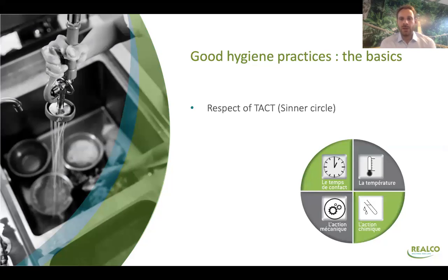Again, the basics. When you have chosen a chemical for the cleaning or a sanitizer for the disinfection, you are going to apply them. And in fact, you need to respect what we call the Sinner circle. For the presentation, we call it the TACT, because it's just an easy way to remember the 4 parameters that you need to respect absolutely to be sure that you are going to have a good cleaning and sanitation. So the TAC means time, action, concentration, and temperature. They are the real 4 important parameters to follow. And I will explain that with the next slide.